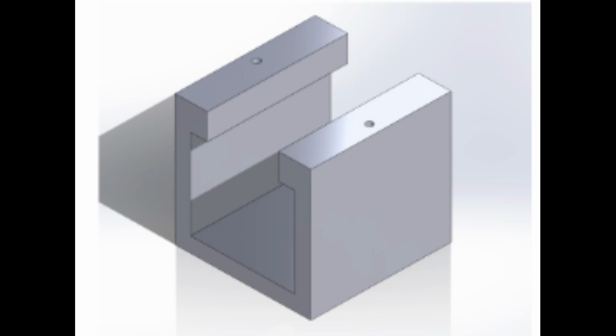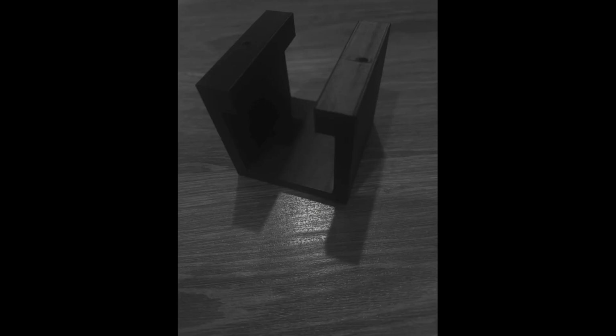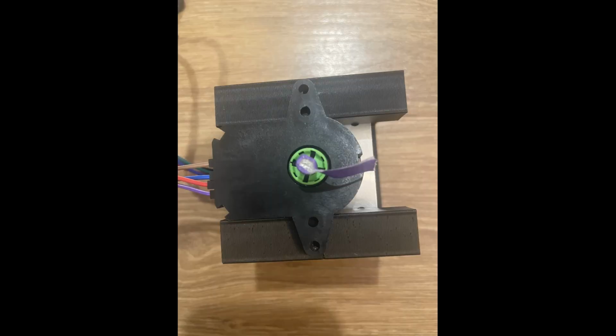A housing for the stepper motor was created in SolidWorks and then 3D printed. It would allow for the stepper motor to be slid into it, then the rotary encoder attached to the shaft, and there were holes that lined up with the mounting holes on the wide base of the rotary encoder. A pin or dowel will be put into the lined up mounting holes to hold the rotary encoder in place as the stepper motor moves.